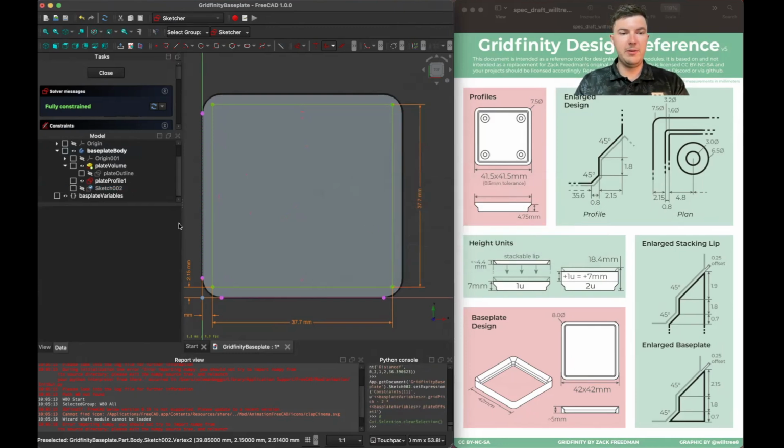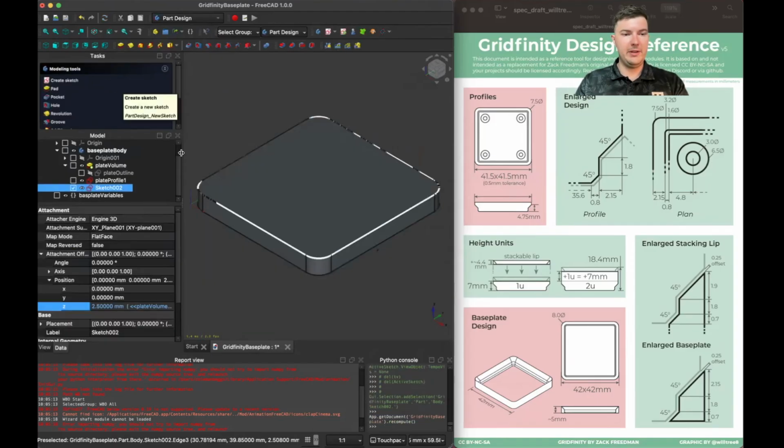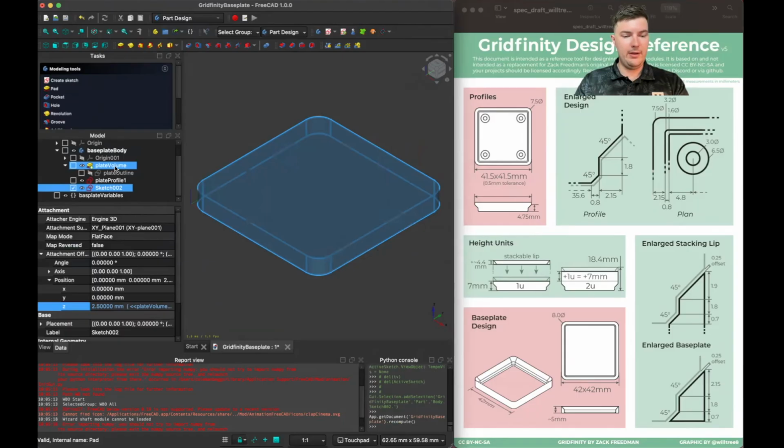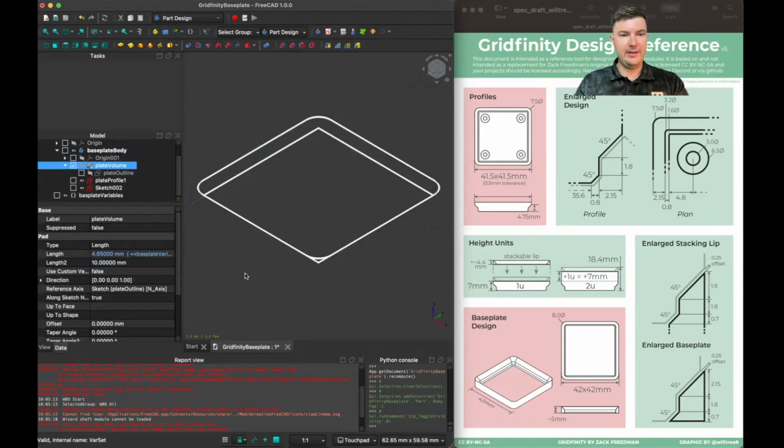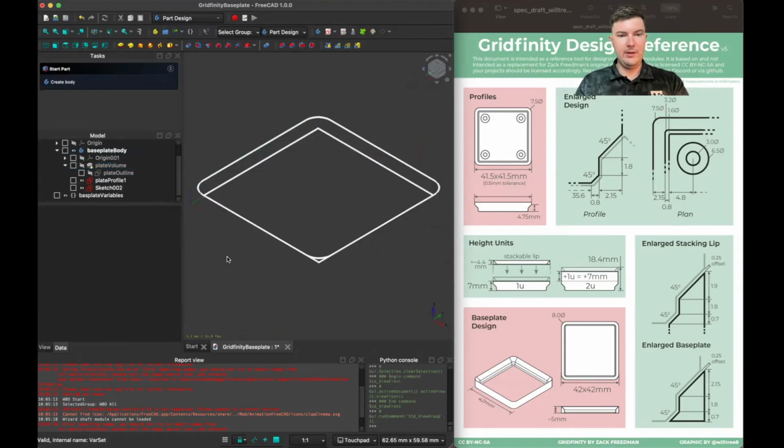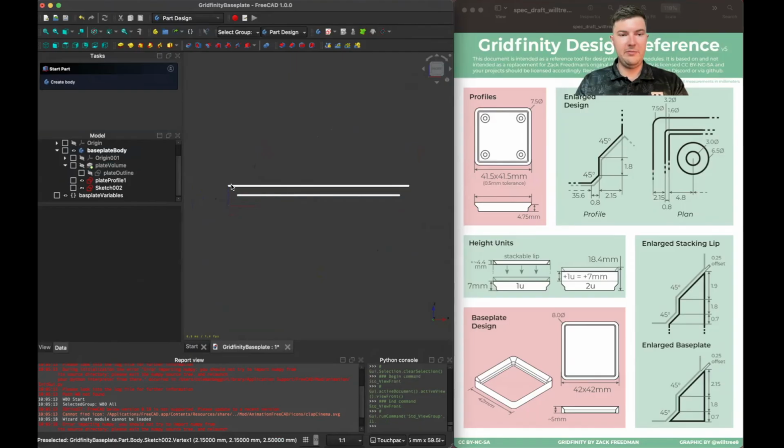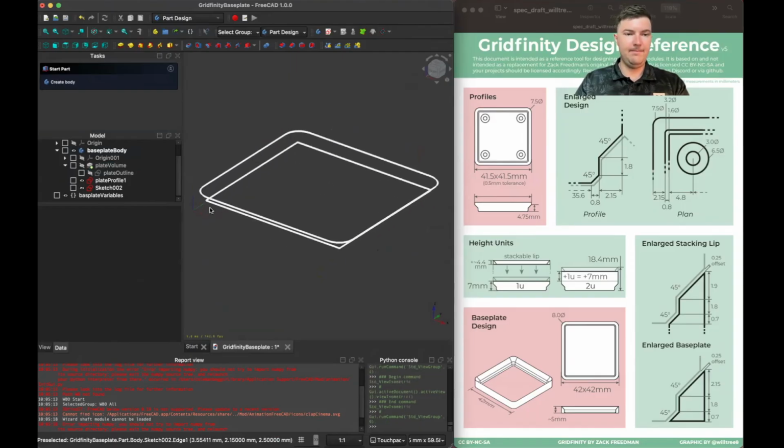And the reason you multiply by 2 is because you're subtracting that offset from this edge and from this edge, or in the Y case, from this edge and this edge. So you can't just subtract it once. Now I'm going to close my sketch. And I'm just going to hide that again. Show you that that attachment offset is already implemented.